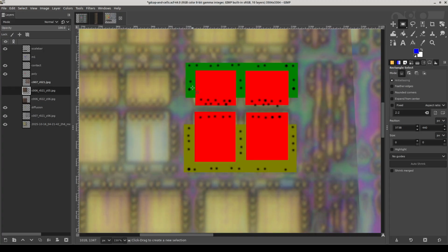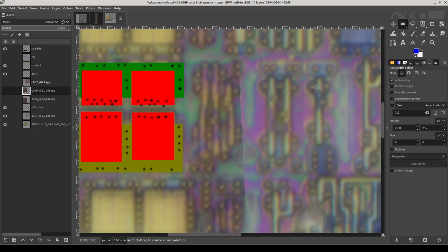But what's interesting is if we look at the layout, we've got a single big piece of diffusion that the poly does not fully overhang. So normally when you have a transistor, the poly is going off the end of the transistor. So seeing here, for example, we have the diffusion region here, and the poly is overhanging it because we want to make sure that the entire length of the channel has poly over it in order to form a transistor. And if we don't have that, then we essentially have extra channel with no way to control it, and depending on the transistor will be essentially either always off or always on and provide a leakage path.